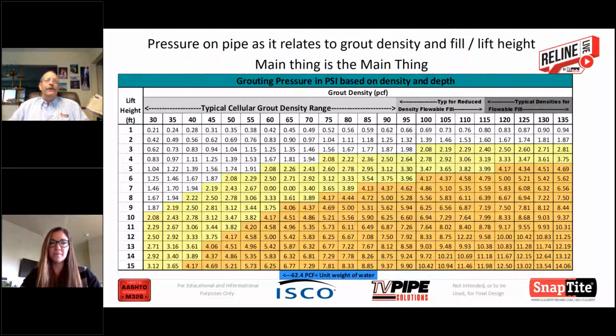If that is a concern, you can certainly put flex restraints or wall anchors on the terminating ends of your pipe, and then you can cast those into your bulkhead. And then your bulkhead becomes a structural member that, number one, helps to hold your grout inside the annulus, and then, number two, prevents movement of the pipe during thermal expansion and contraction or temperature changes.